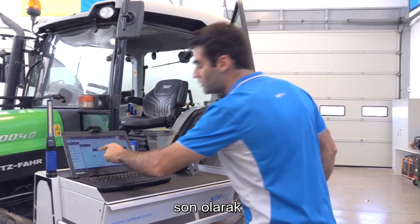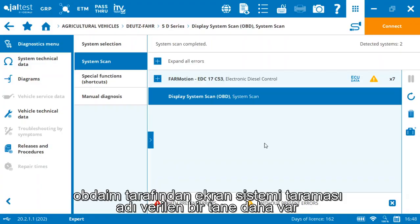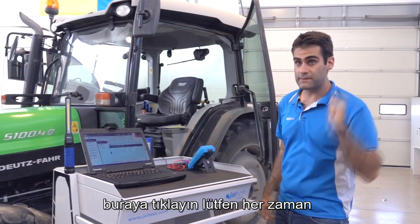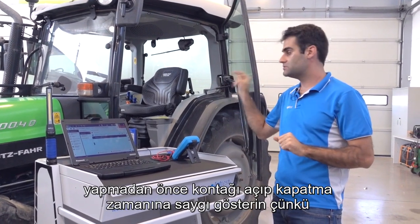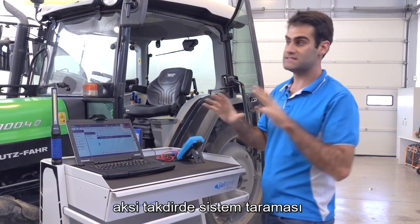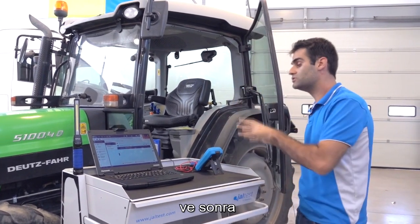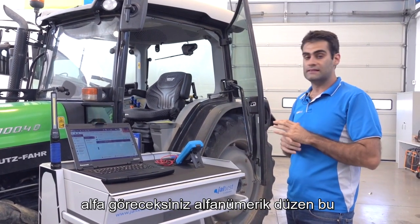Finally, we've got another one which is called Display System Scan by OBD. Click on here. Please always respect the time to switch on, switch off the ignition before doing it, because if not, the system scan will not be correctly done. And then you are going to see an alphanumeric layout.